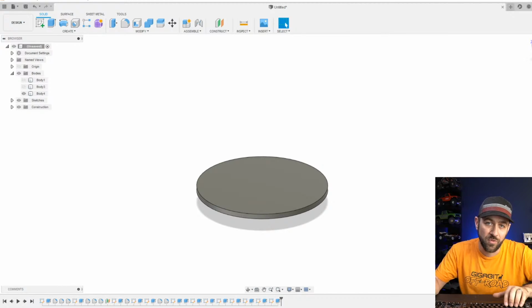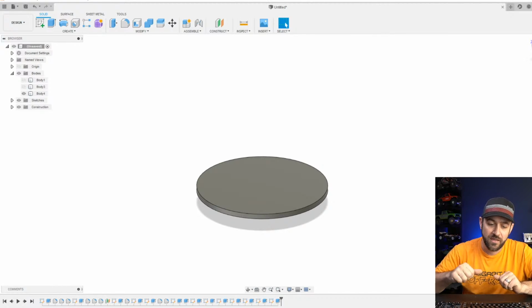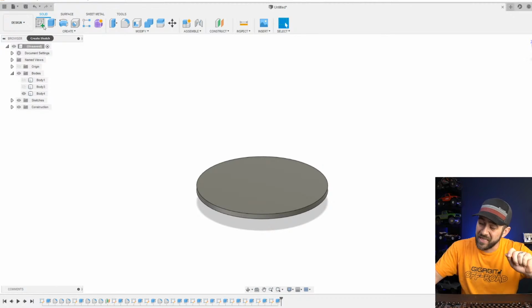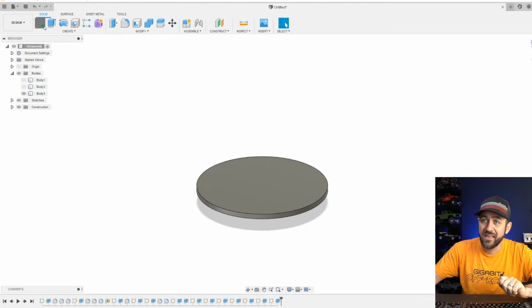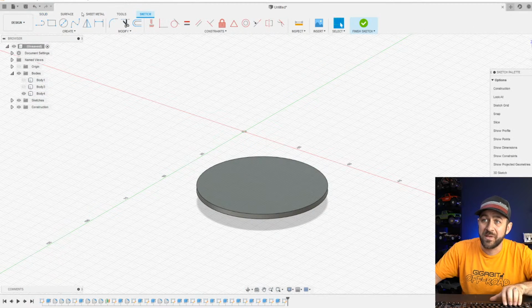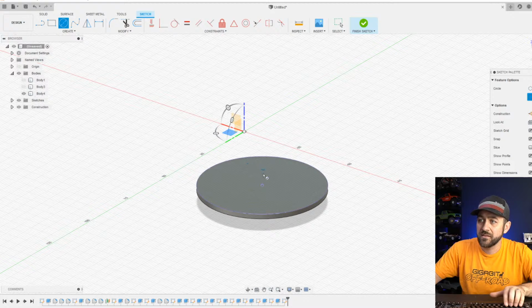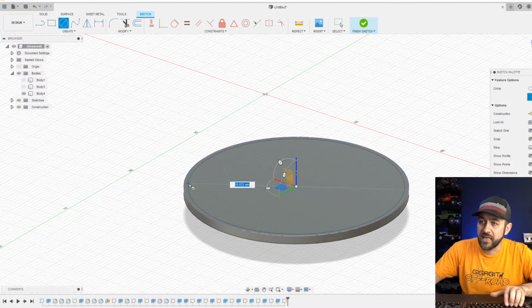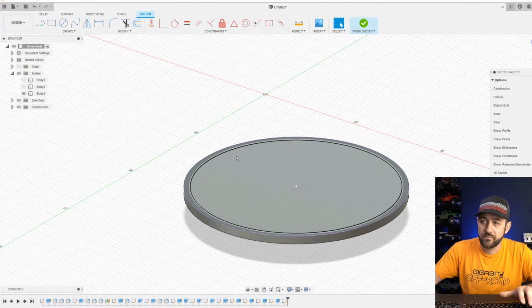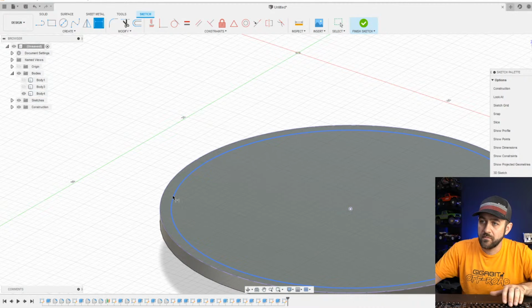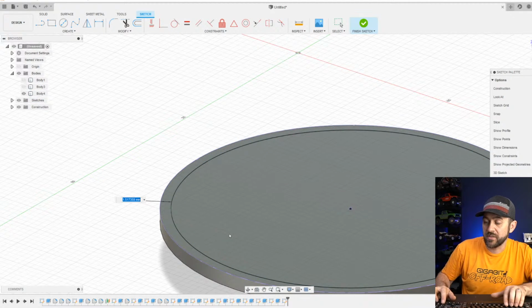Make it 11.1 so that you have a little bit of wiggle room. You can tune your printer to be dead nuts, maybe, but you might get a different roll of filament and it might be different. So just give yourself a little wiggle room when you're designing so that you don't have to worry so much.